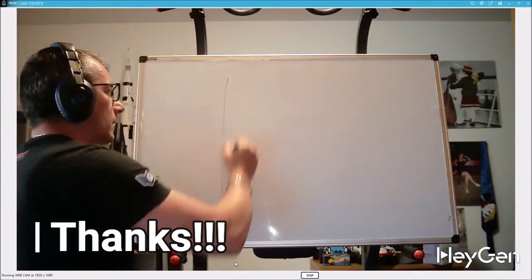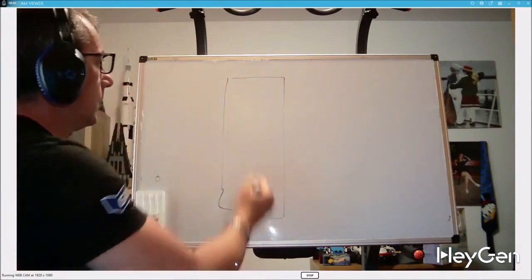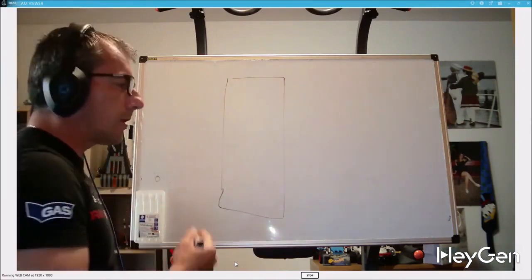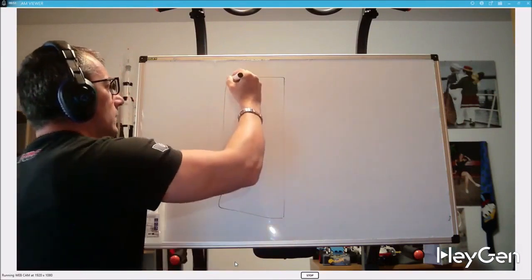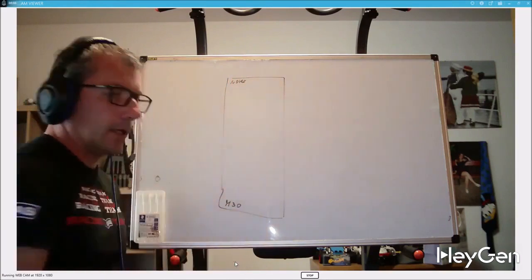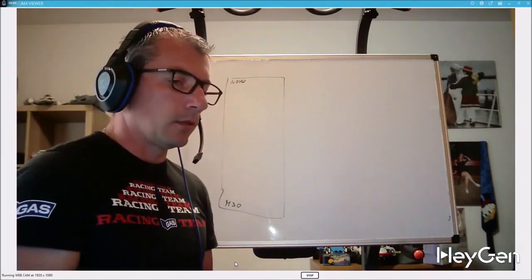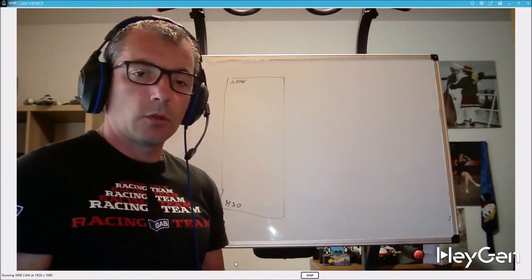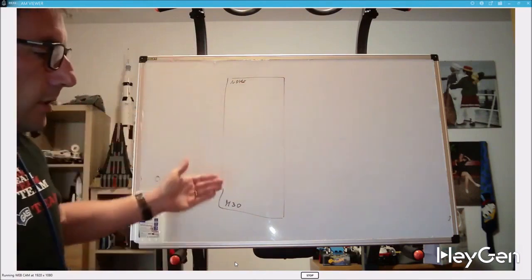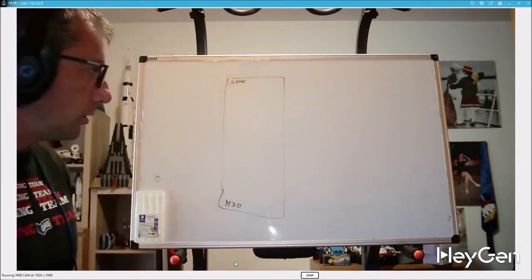Let's think about a program, or the main program, the one we typically write, that has its own beginning and end. When writing the subprogram, we will insert some codes, definitely, including a name and a final M30 code. Keep in mind that I'm using a simulator that's mainly FANUC, especially for the macros. But what I'm trying to do is give you a general overview that applies to all machines. You can find subprograms in all lathes.